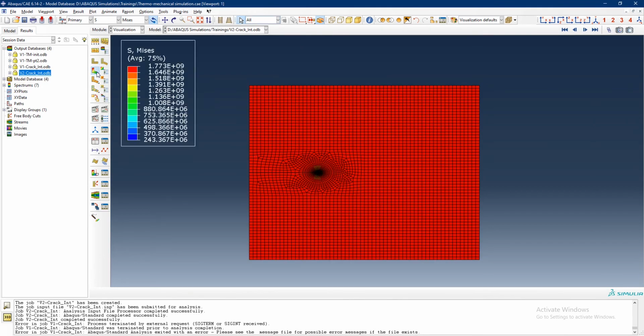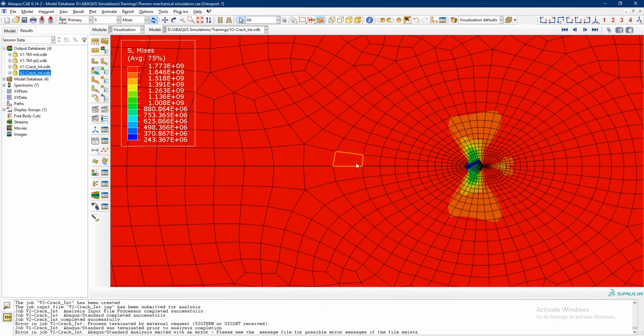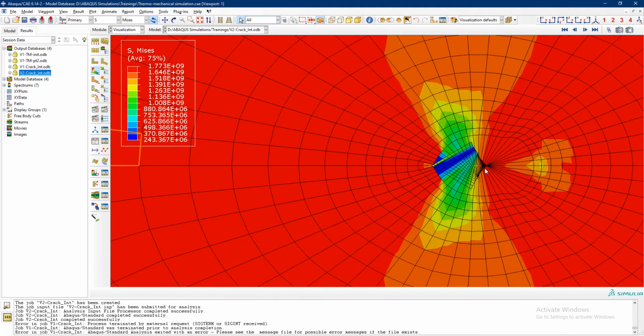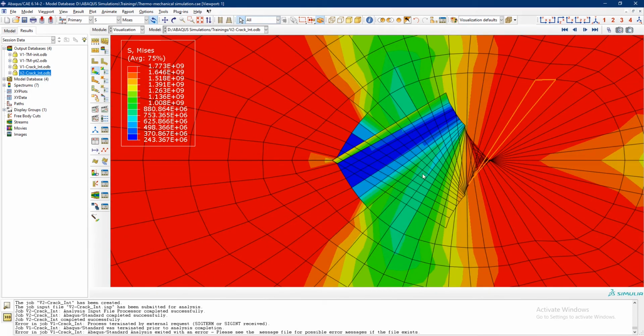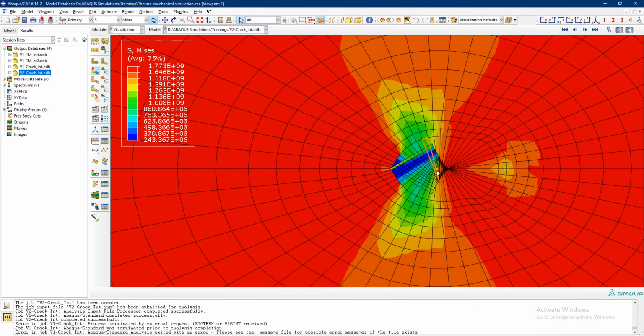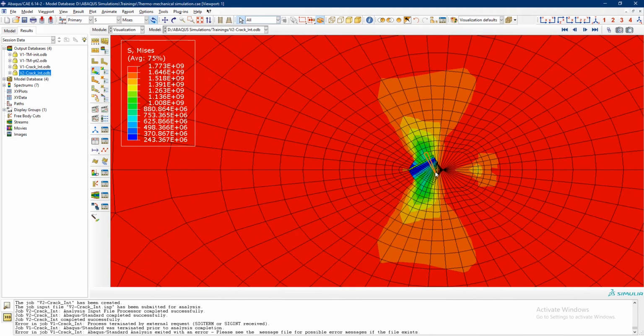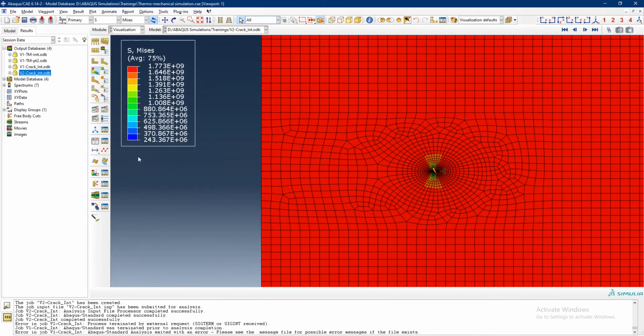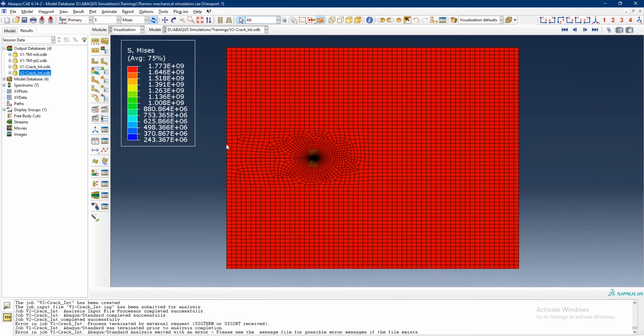in version 2 of the simulation, you can see that there is no overlap here. There is an overlap here in these nodes because we did not define the crack face interface, and this is a problem with contour integral crack, that we unfortunately just cannot define a crack interface here on this element. But this is a very small problem as compared to the rest of the case, and it does not really affect the results when we are applying thermomechanical loads, because this overlap is really super small.